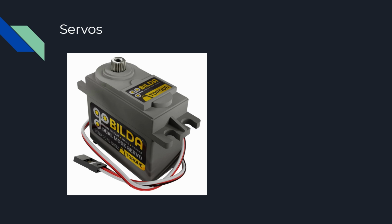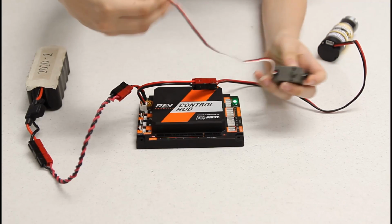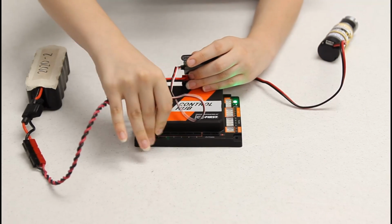Usually if you have a dual mode servo like this, you can set it to continuous or regular servo mode on the servo programmer. In our case, we're going to be focusing on regular servos, since continuous rotation servos can be programmed very similarly to the way that we did a motor, just replacing the motor object with a continuous rotation servo.